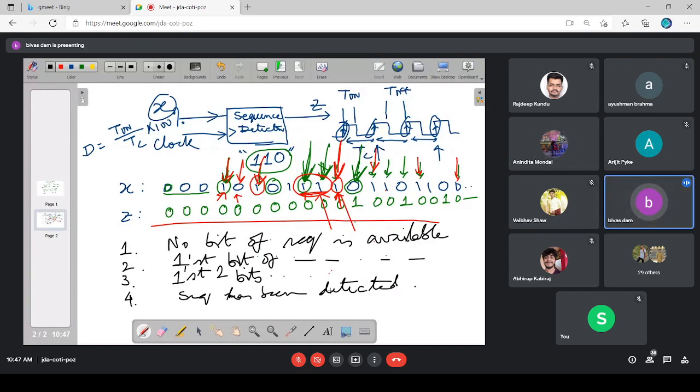Only the binary language, 0 and 1. So now comes the most important thing. These histories which you have obtained from the problem description must be represented to the digital circuit by binary patterns. So I must be able to encode this history information by some binary codes.